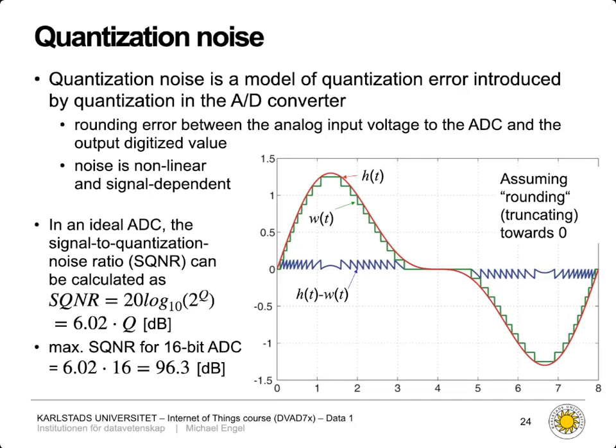So you hear this noise as audible noise, and this is exactly what happens here. You cannot ideally reconstruct the signal, so you have this difference to the original signal, and what you hear is noise in your speakers or headphones when you have a signal with a low amplitude resolution. This is exactly this blue line of difference that you're hearing.